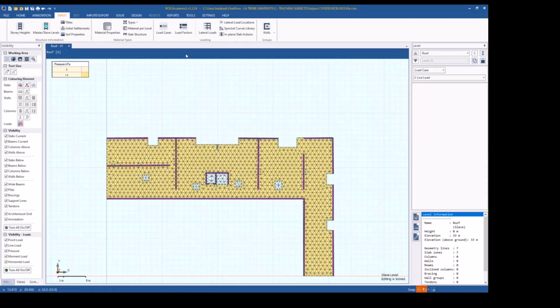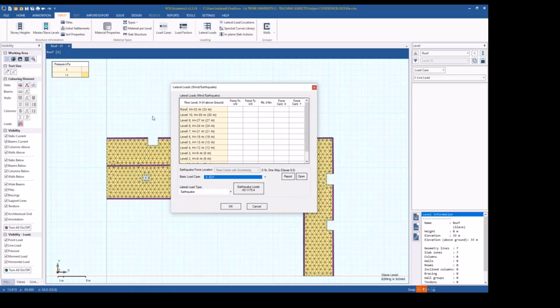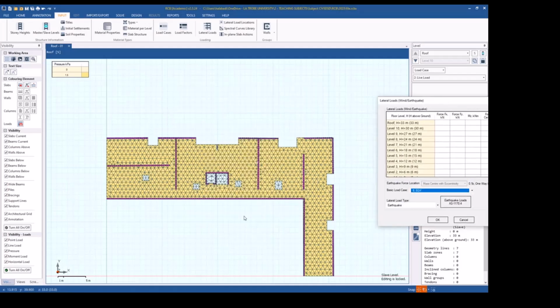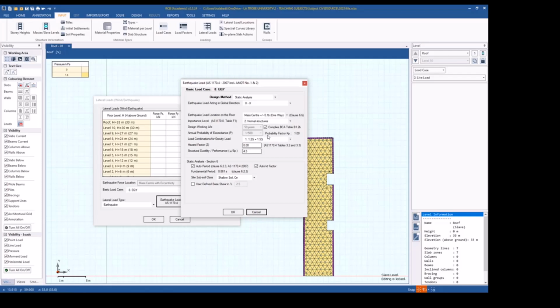Now we're just going to follow what you did with your calculations. Go back here, go back to earthquake. Let's do the full Y, because Y is coming down the page, that's what you did. So here I will do case number 8 first, click there, and that's YY. Don't worry about changing all those, leave them as they are. I think in your case you just have this 0.9, that was clear.